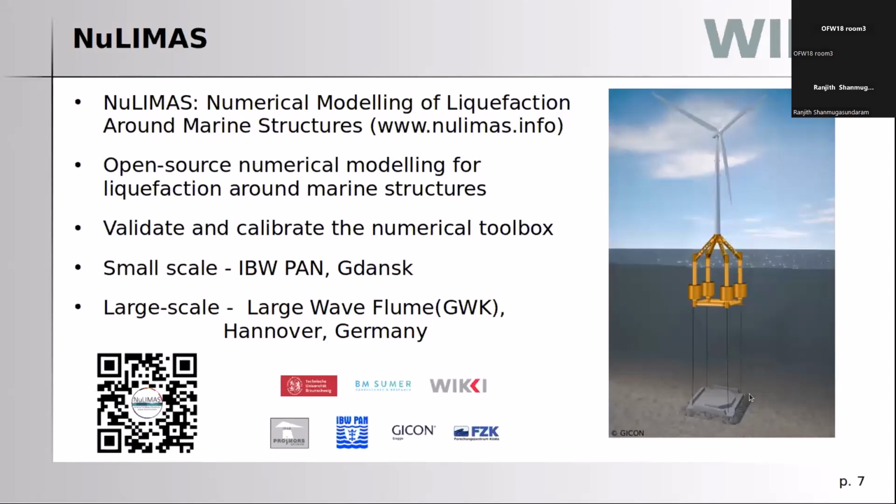And here is actually the gravity anchor. It is based on the seabed and is connected to the turbine with the help of rope forces. So whenever there is a loading, you can see that the liquefaction starts to develop, and then it is collapsing the anchor, and then we have a lot of damages, and that is what we wanted to predict with our numerical model.